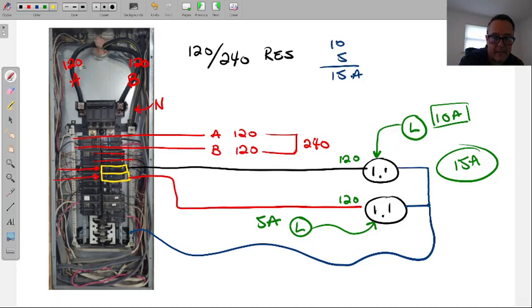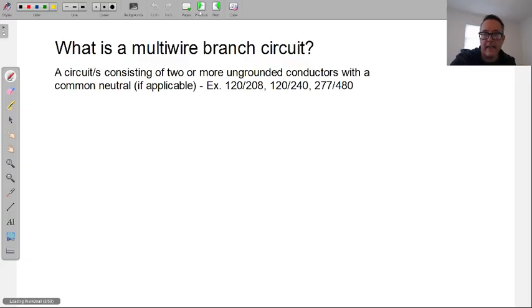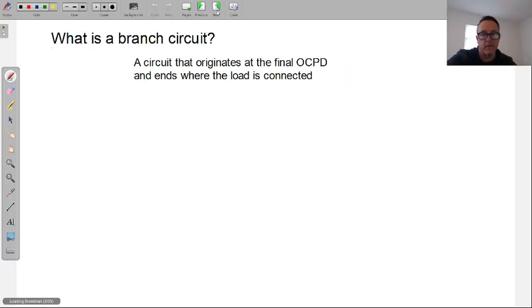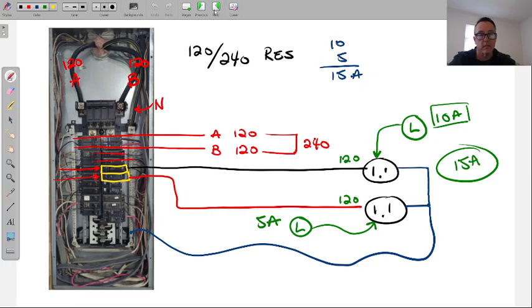So the breaker, let's say both of those breakers are 20 amp breakers. What the 20 amp breaker is saying to this circuit is the most you can plug into each of these individual outlets is 20 amps. If you plug in anything more than 20, I'm going to trip. And this is why, getting back to this add-on to my definition, breakers aren't providing current for the circuit. They're just making voltage available at this outlet.